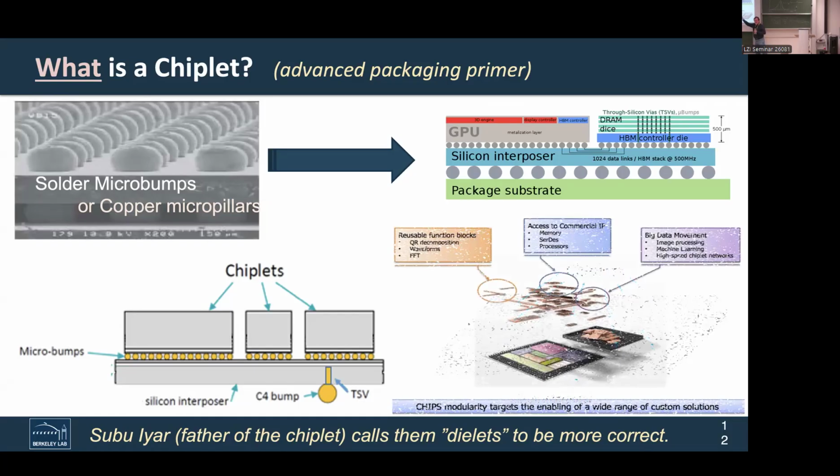With the modularity, you have the opportunity to have 90% of what's on the chip be kind of boring stuff: PCIe, memory controllers, caches. Then you can isolate the stuff like that FFT chiplet that you want to contribute, and it's a much lower cost. I have a tinier chip that I'm making, but I get almost the bandwidth of it being co-integrated, and I don't have to own the entire chip. I only have to own the little piece of accelerator that I have.